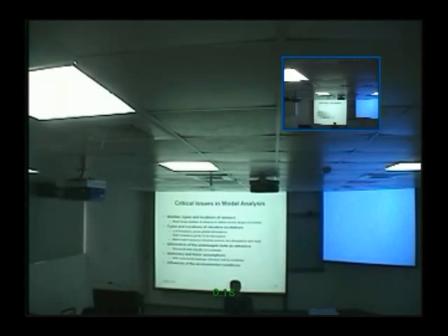Many bridges, if you measure in the evening and measure in the mid-afternoon, are totally different. And the signal change from the ambient temperature can be stronger than the damage. So if you have only say 30 sensors, you put them in one section and measure in the morning, the middle section at noon time, and the other section in the afternoon. You measure 3 different bridges because the temperature is different.